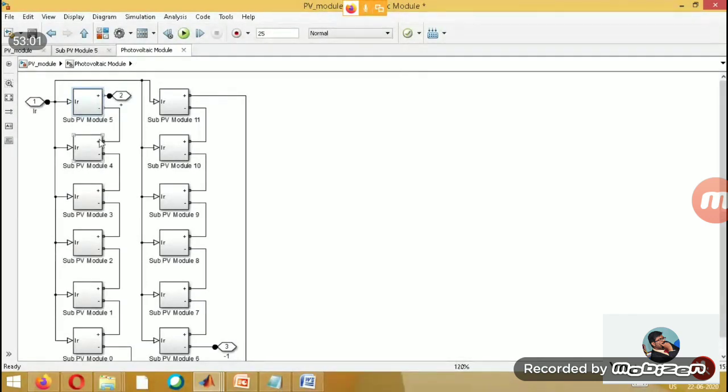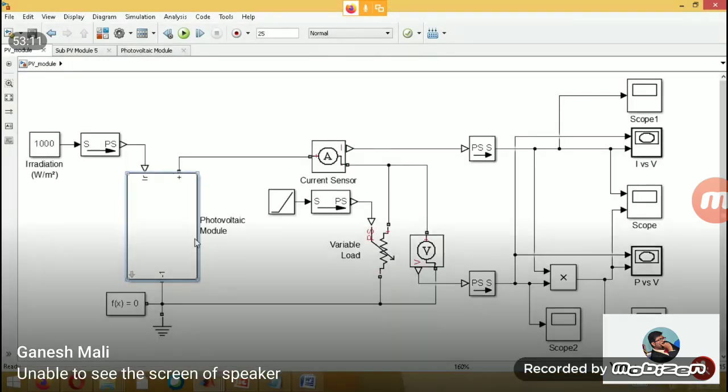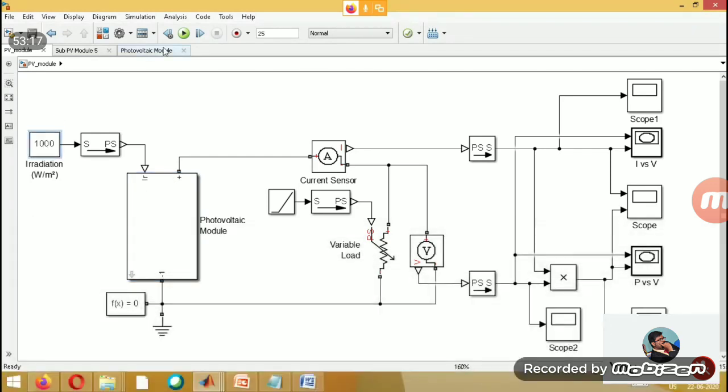See, negative is being given to positive. Again this negative is connected to positive. So only it will become series. So connect all of this. So once you connect all this, you get the entire setup now. And this setup is in Simscape. So this Simscape cannot be connected directly to this block, which is nothing but a constant block.